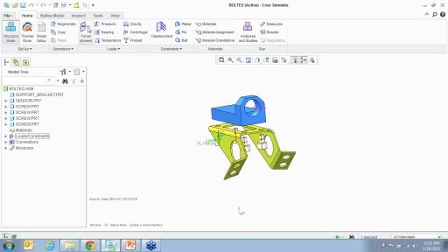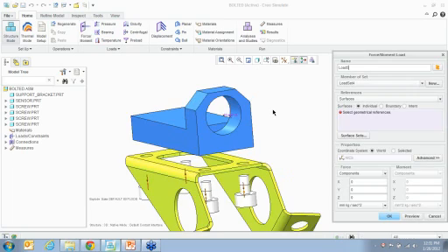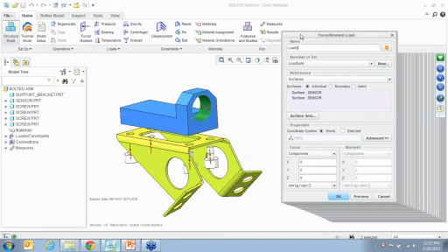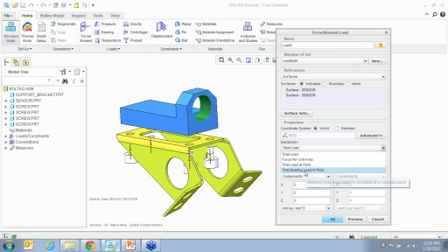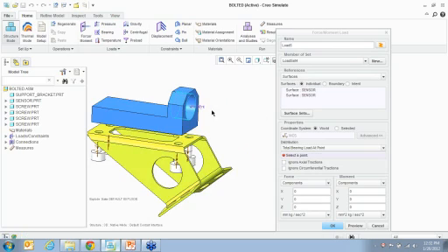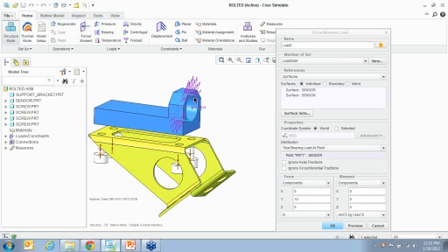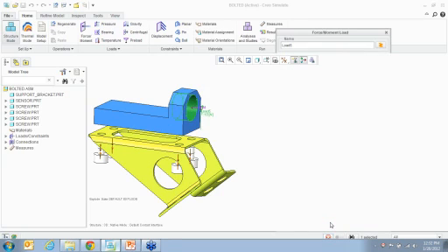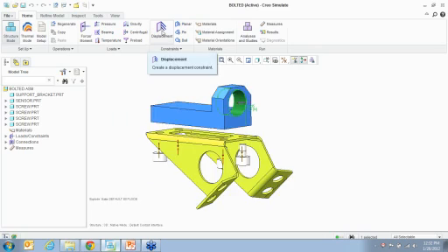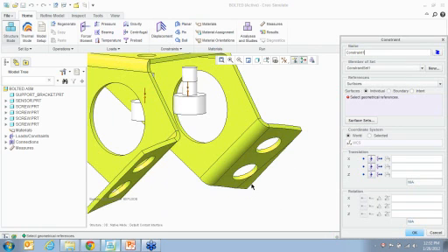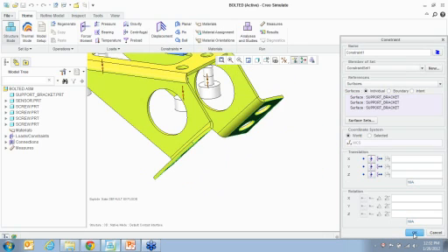Now I also want to put a force load on this surface. Here a new enhancement would be total bearing load at a point. So I say total bearing load at a point, and I'm going to pick a point right here and say it's acting in the Y direction at 1,110 newtons. You can look at the preview because it's a bearing load. If I stick in a rod in there and then push the rod up, notice that the front half of that particular hole gets pushed up and the bottom half pushed down. It's a more exact simulation of what happens in real life. Then let's say displacement, we're going to fully fix these particular surfaces. So fully fix, I don't want them to move.